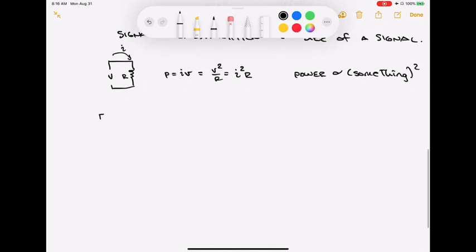So let's talk about energy signals. In this class, when we talk about the energy of a signal, we're just going to write E sub x, read as the energy of x. It's going to be a limit as some parameter T goes off to infinity of an integral from minus T over 2 to T over 2. So basically, I'm going to be looking over an infinite line of the signal's value squared dt. This is the way the book does it. I can tell you right now, I'm not a super big fan of this notation.